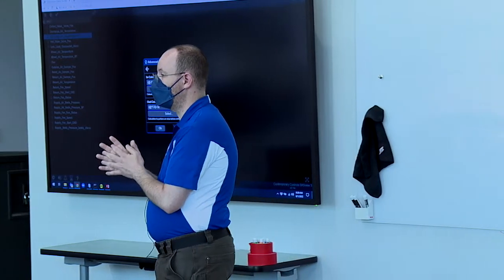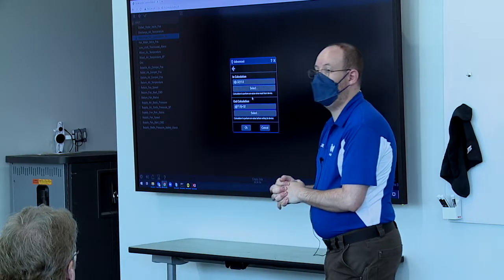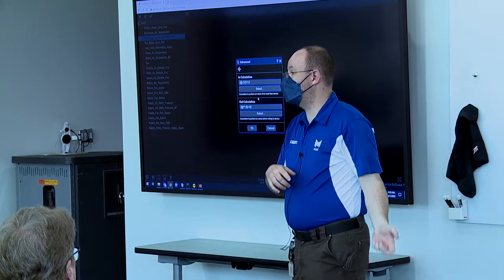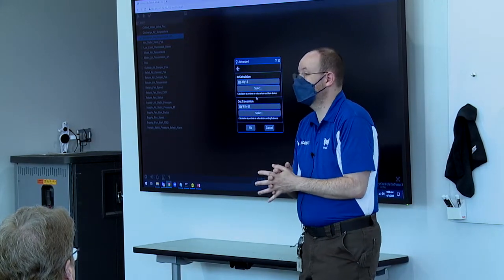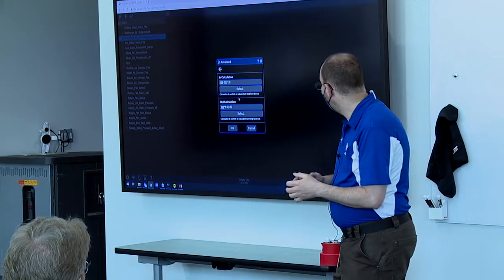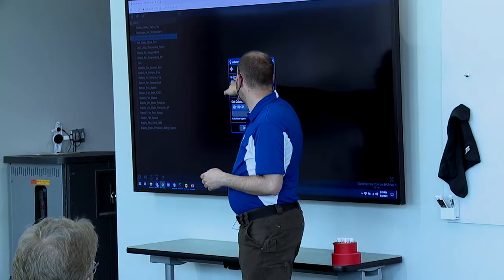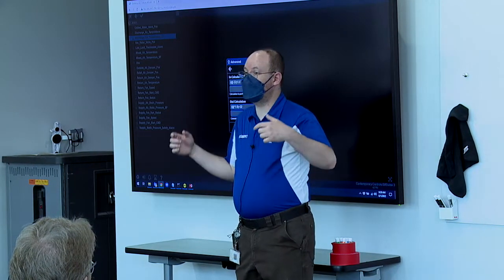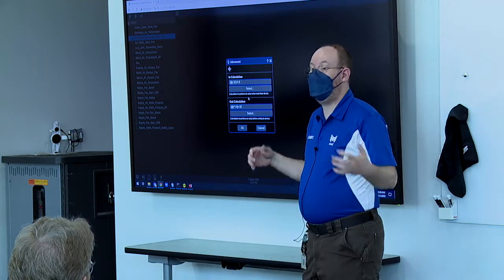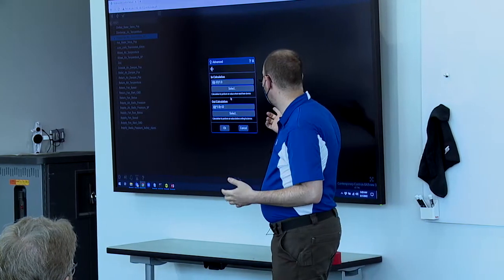If you're selecting these conversions, can you write your own? Absolutely, yes. To Sean's point of taking an air velocity and converting it to a CFM, that would be a great example of writing your own. You'll have to be a little bit careful with the syntax. You notice this @ symbol here? That is our value that the point is getting. So that's our X value, if you will. So you always have to include that.